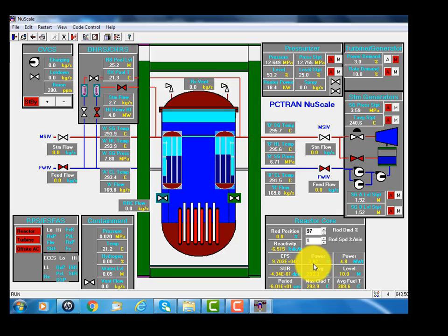so that the decay heat right after reactor shutdown, which is about 3% or about 4.7 megawatt, will be removed by the heat exchanger. If both trains are operated, they're redundant. One is enough, but two will be available. So the core decay heat will be removed by the passive heat exchanger.